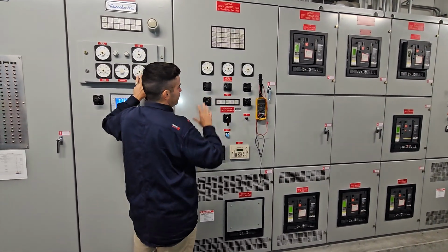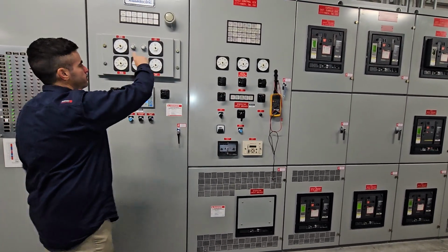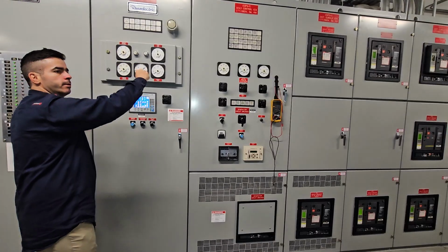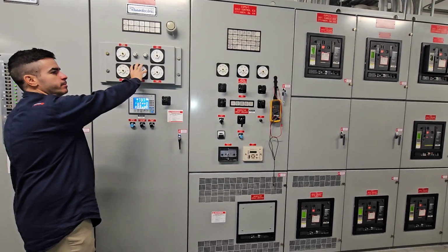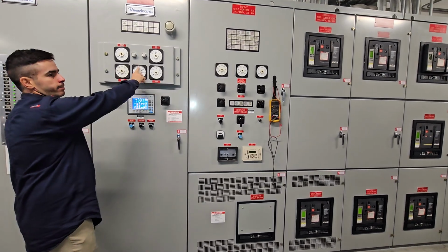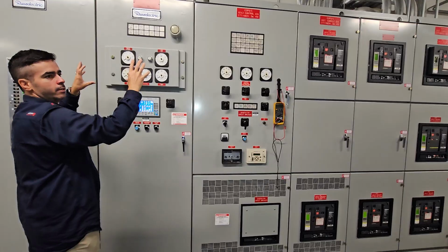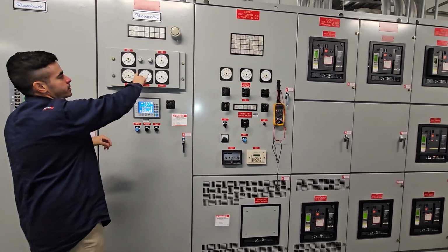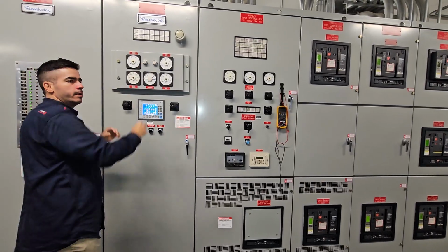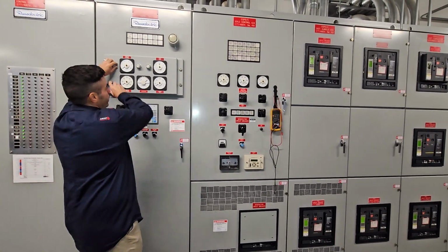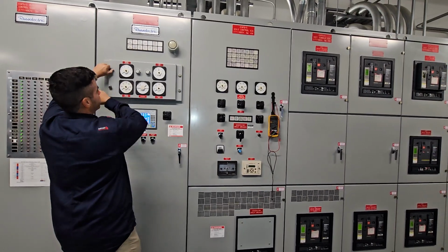So if all that looks good, I'll put this one on, and then I will see the synchroscope start swinging around. The safe position to close, because this is telling me when it's in phase, is at 12 o'clock, right? These lights will be bright if I'm at 6 o'clock, and then less bright as I get closer to 12. So when I'm at 12, these lights shouldn't be on. When I'm doing that, I have to watch this. That's why this is a swing panel, so I can move it this way or this way.